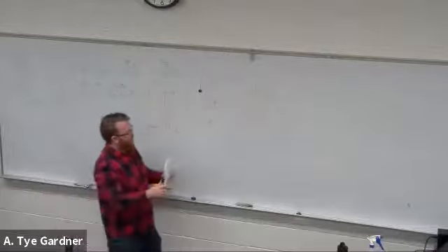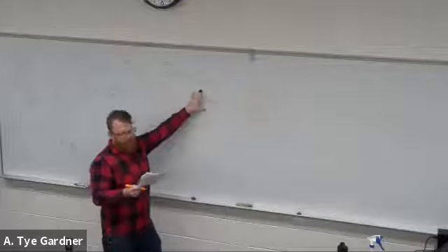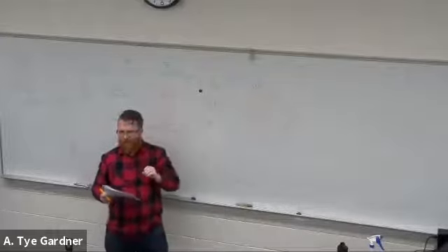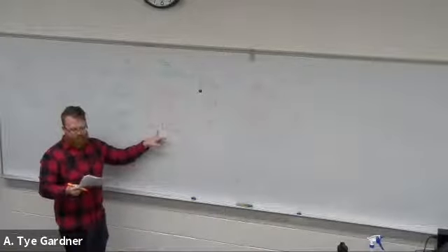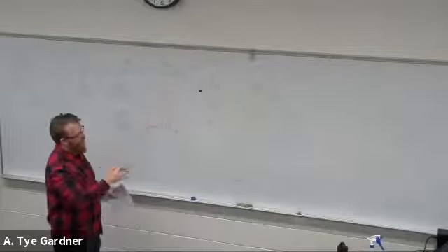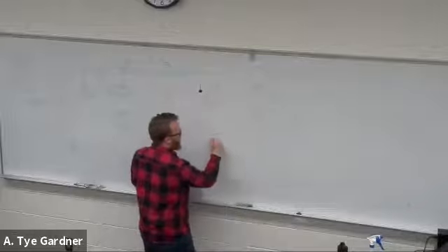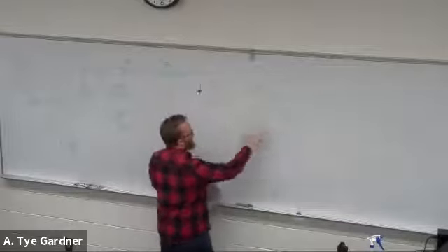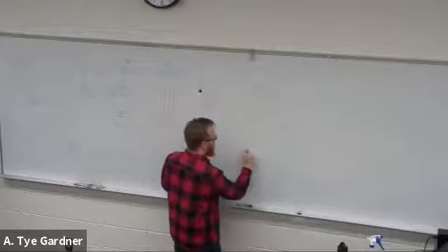Now, in general, the reason that our sensitivity kind of sucks is because this gauge factor is usually about 2. So it's not very big, and that's for this type of wire conductor. They like to describe things a little bit differently and arrange it as delta R by R is equal to, and we're just going to move epsilon up to here, gauge factor, and I'm actually going to write it as G.